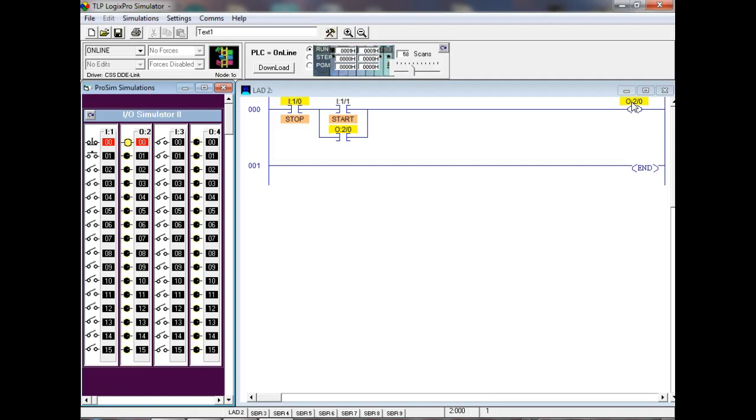because it's going to do it wrong, right? So now, if the wire that's connecting my push button to my input port opens, then it says examine if closed. Now it goes open and the motor would stop. It would drop out like this.